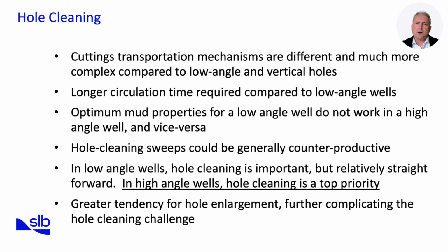In short, hole cleaning becomes a top operational priority in ERD. Poor cleaning leads quickly to pack-offs, stuck pipe, or excessive drag. Next, we'll move to another critical operational issue in ERD wells, tripping and wiper tripping practices.